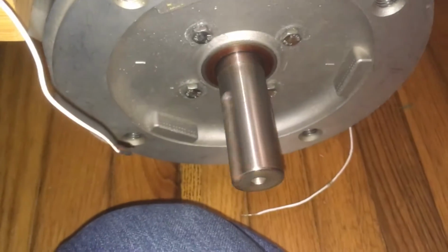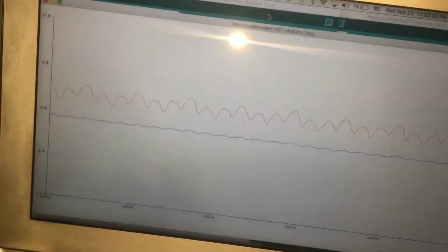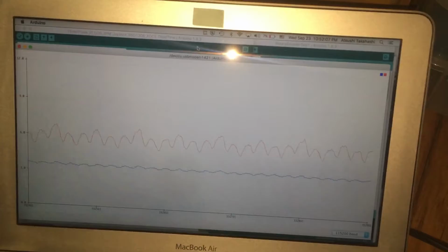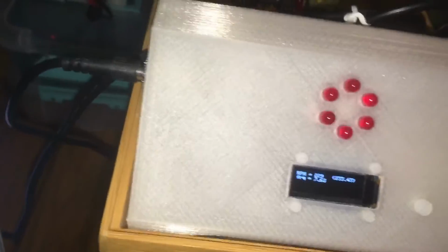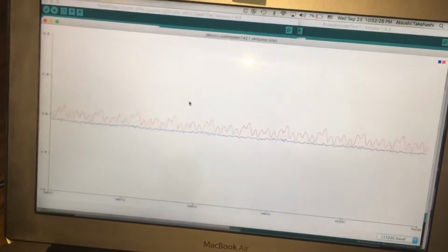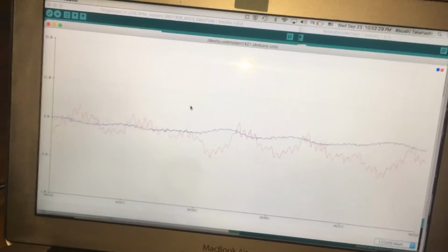And when we hit that spot, you see that the motor just starts turning, and we're drawing quite a bit of current here. This is probably like 5 or 6 amps per channel. So let's quickly get past that high current zone and move up to roughly 10 hertz here, or about 300 RPMs. And you can see the RPMs is slowly coming up, and the current is about 9 amps right now.